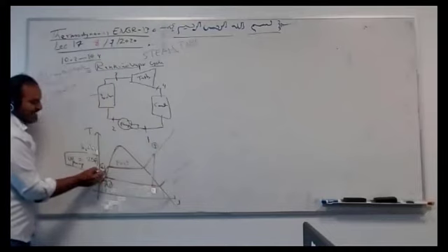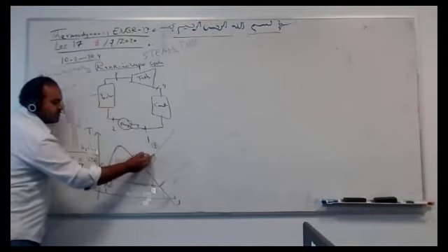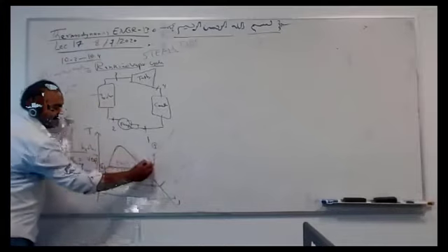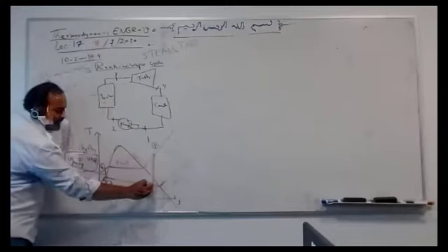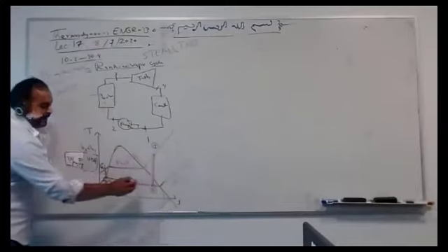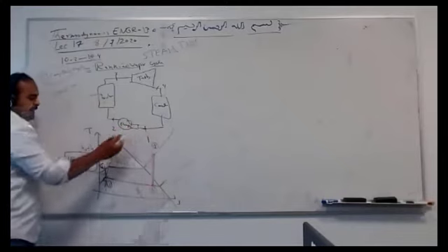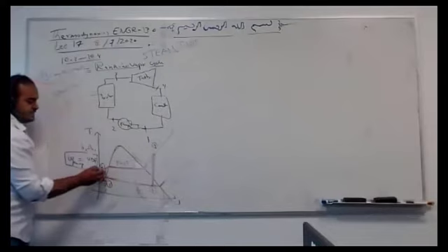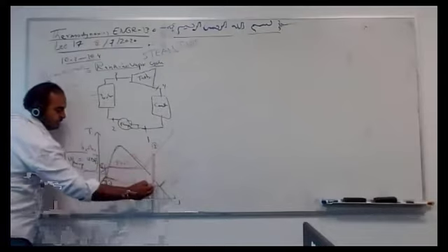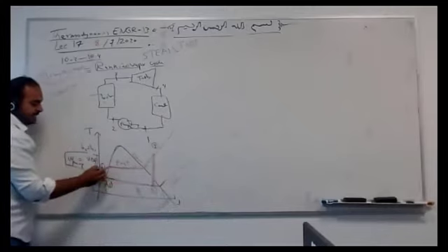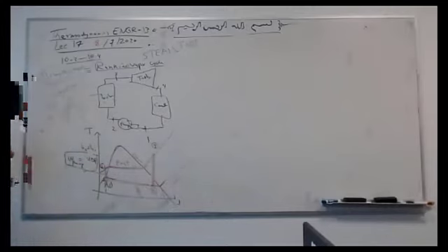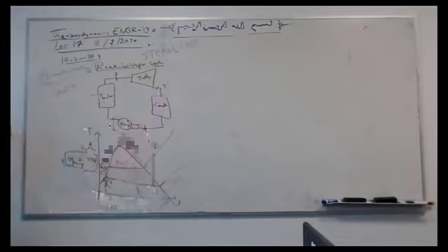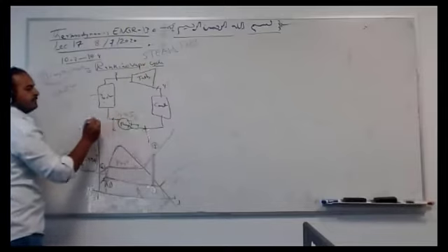So what happened? I compress isentropically, burn at constant pressure in the boiler, pay fuel, Q high. Then expand in the turbine. I wish to go vertically. Then dump heat Q low in the condenser. Then go back to 1, making it a complete liquid again. Compress, burn, expand, condense. Compression and expansion are isentropic, of course, constant entropy. It means S1 equals S2.